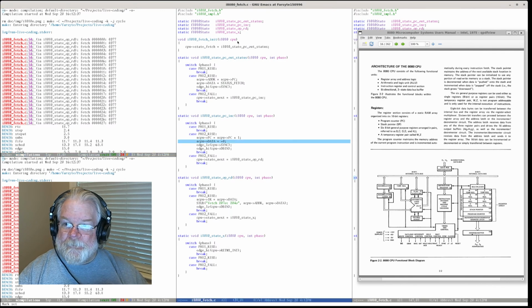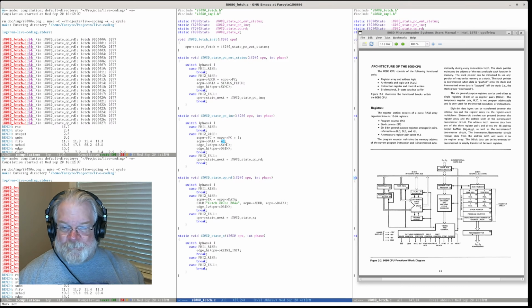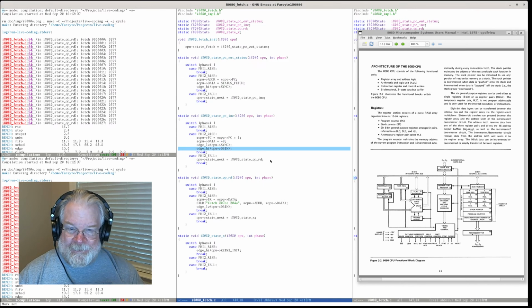So we only output our status byte for this period of time, from phi2 rise on the T1 to phi2 rise on the T2. And then I'm setting it to all bits set to be a visible "I got nothing." Okay, so this means that somebody else is going to respond to the data bus here and give me some data.